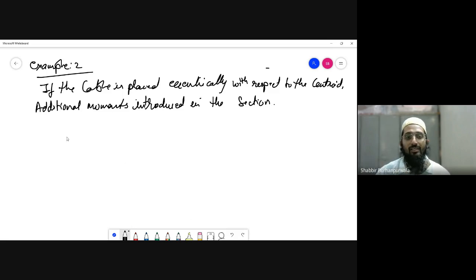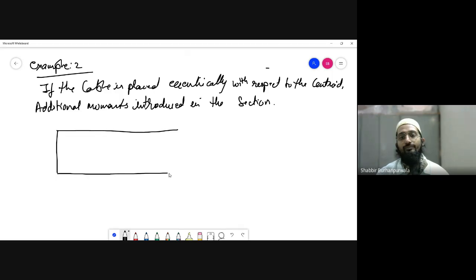Let us make the same longitudinal cross section of the diagram and provide the same type of support. It is hinged at both ends, so there are moment releases at both ends. At the end support, the moment because of the external loads is going to be zero. Now what do we see over here?